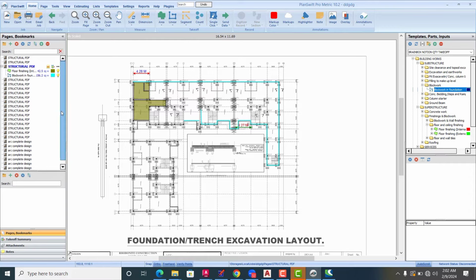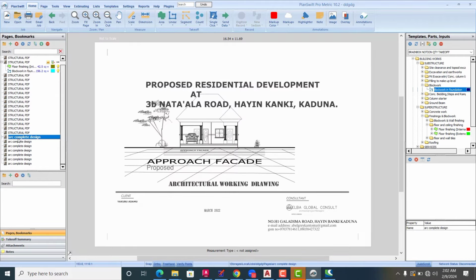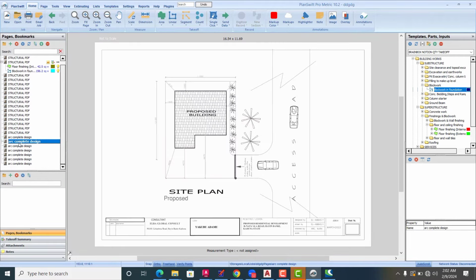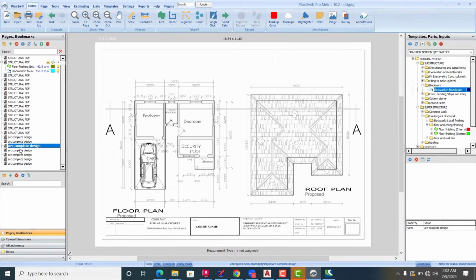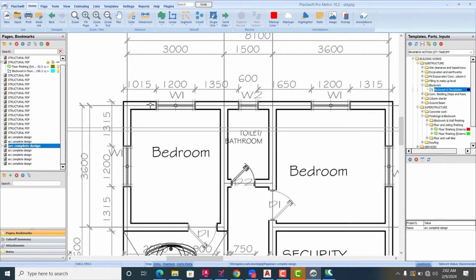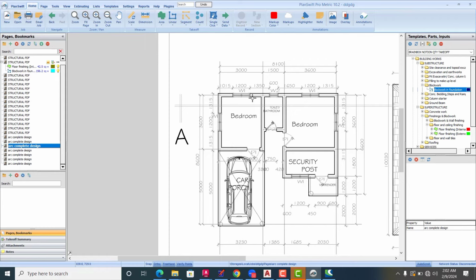You don't know what is the roofing. See now, beams, and then see, this is an architectural drawing. For example, in my architectural drawing, I want to introduce a lintel for this. Lintel here, lintel here. In Ghana, we normally do the lintel all over the perimeter. So however you want to do it, it's the same principle that you can replicate for however you want it.